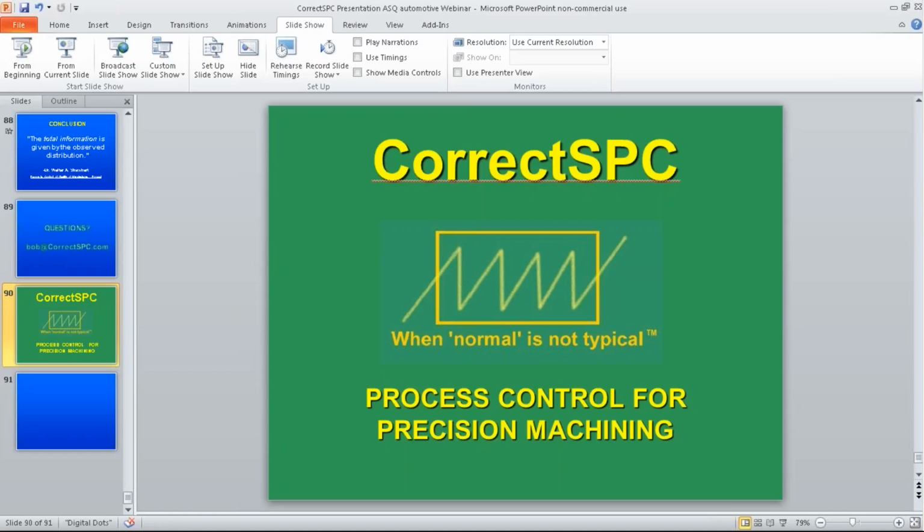So therefore you should be doing regularly scheduled, or? I wouldn't use automated tool wear adjustment unless I absolutely needed to for some particular reason, because like I say, it masks important information that will help you use your tools longer and understand what condition your process is in, and understand how well your tools are working. All this information is gone, totally gone, if that's what you're using. In fact, if you're using automated tool adjustment, there's no sense SPCing it. It's not going to tell you anything because it's totally over controlled to begin with.